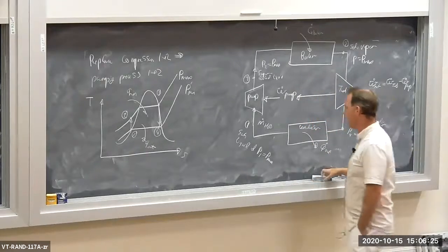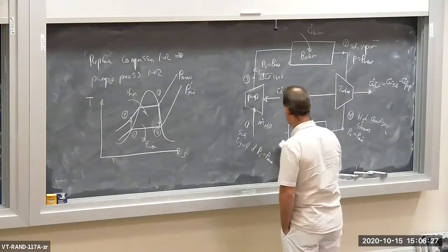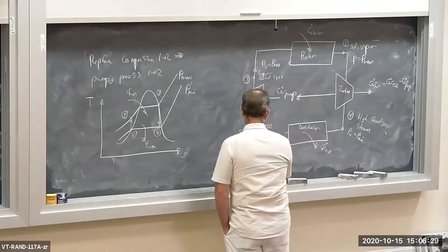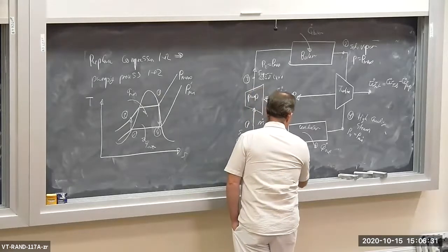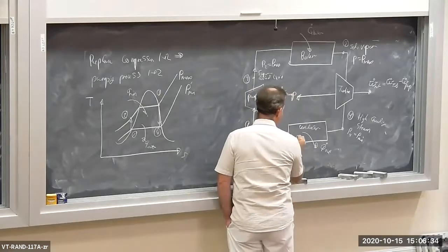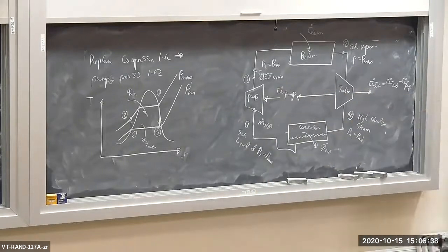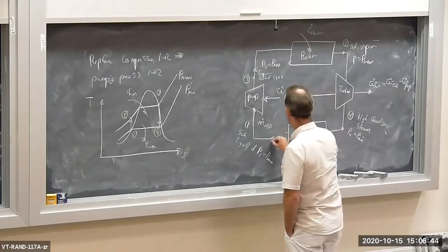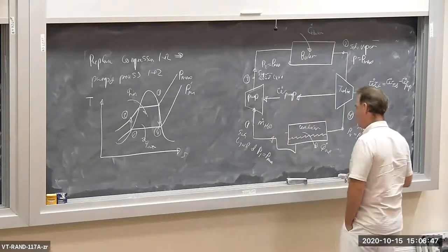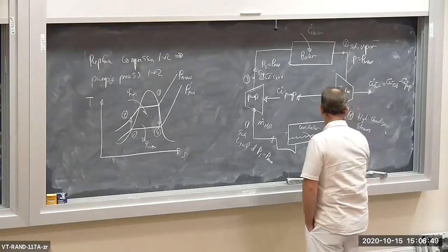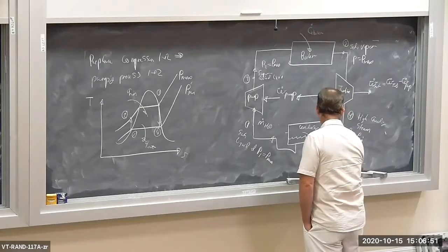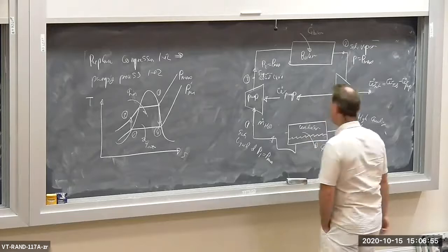If you want to know how this physically works, basically, steam comes in, heat gets rejected, and we get liquid saturated at the very bottom of the condenser. And that gets pumped back to the pump. Okay, that makes its way back to the pump. So this Q dot out is Q dot condenser, okay?